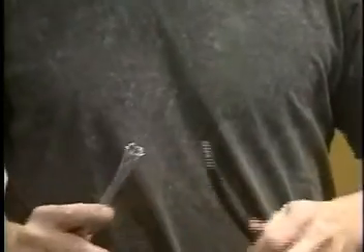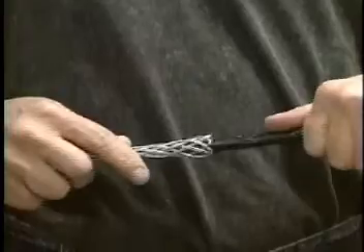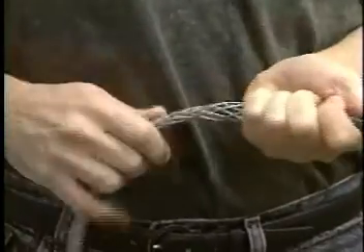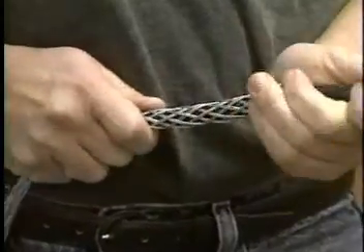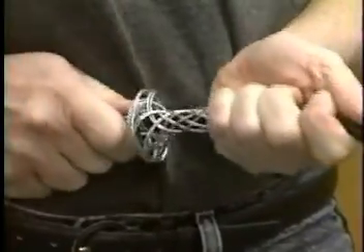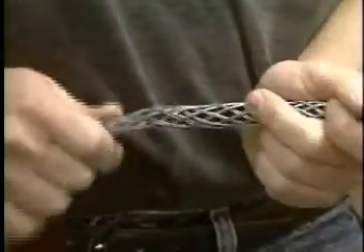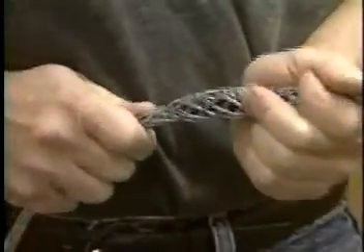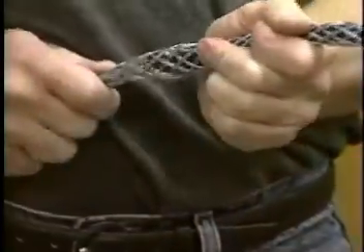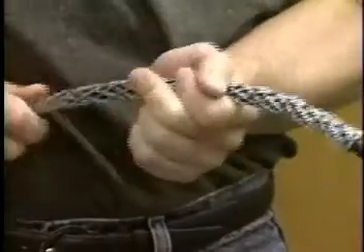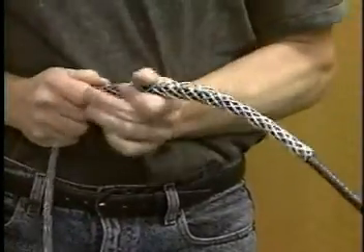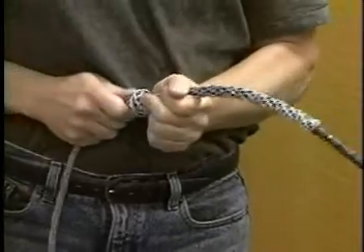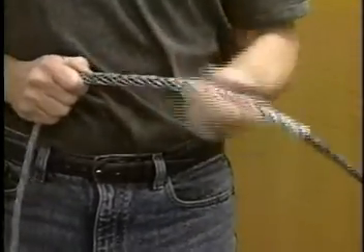With indirect attachment, pulling forces are distributed over the outer jacket of the cable structure. If strength members such as aramid yarn are located beneath the jacket, a minimal amount of stress will be transferred to the fibers. A common type of pulling fixture in use is the Kellems grip. It is reliable for cables as small as 0.6 centimeters in diameter, all the way up to the largest diameter fiber cables in use today.